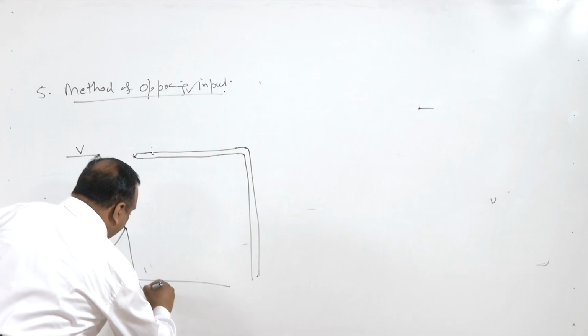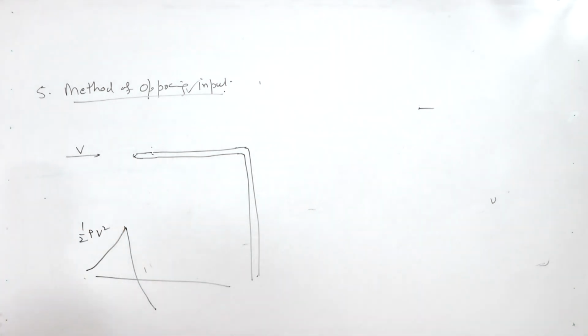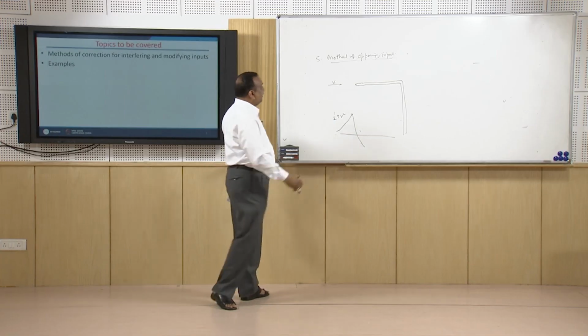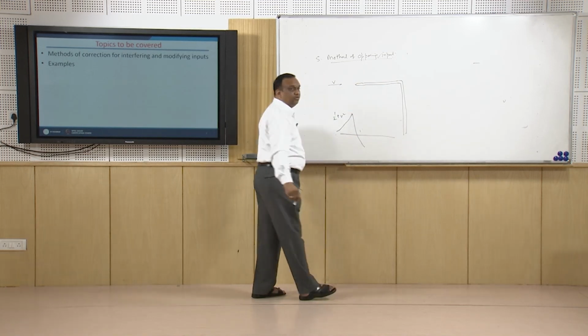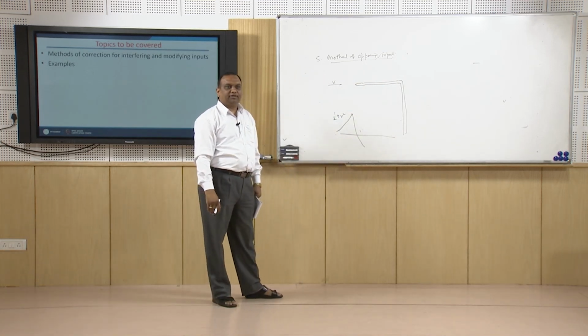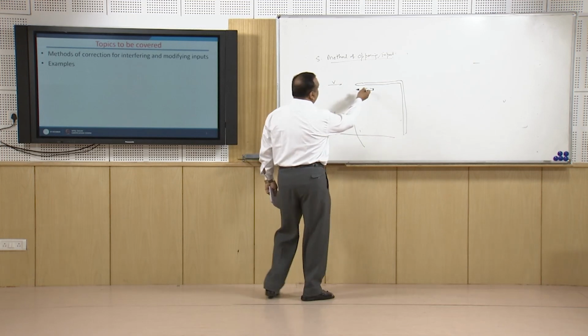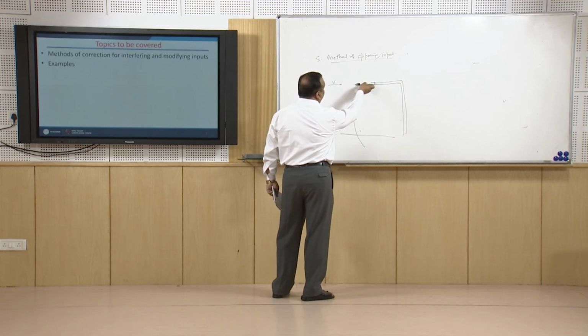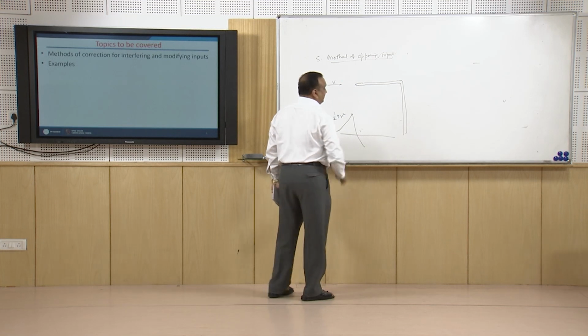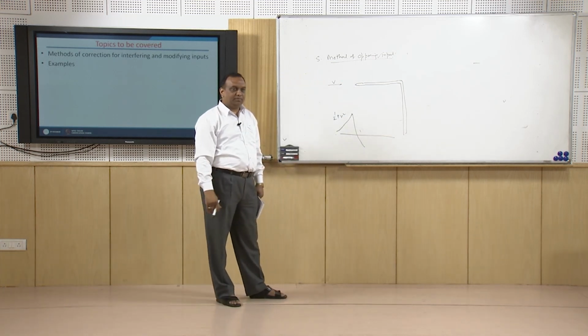There is a sharp fall in pressure due to high velocity of the fluid, right? And high velocity because this probe is placed here, and it has increased the velocity of the fluid in the vicinity of the skin of the probe.